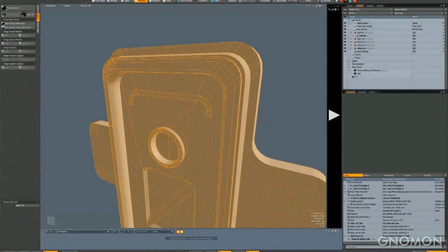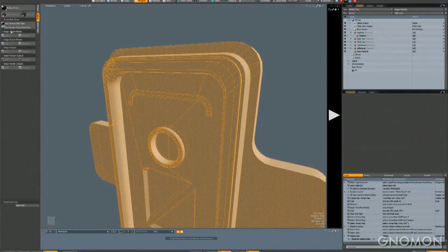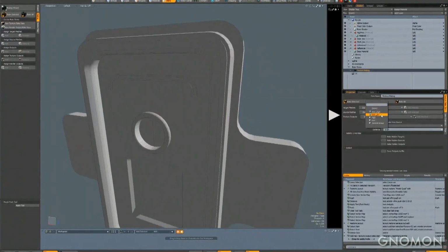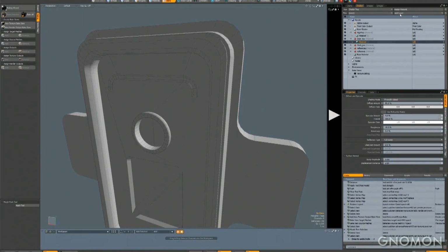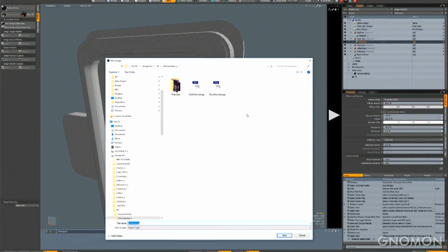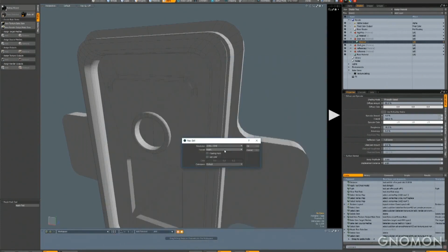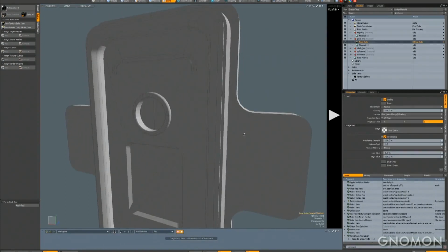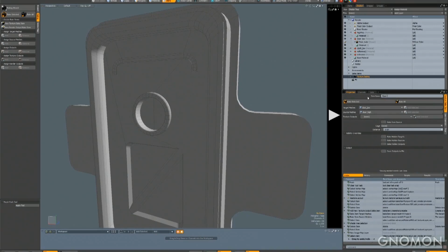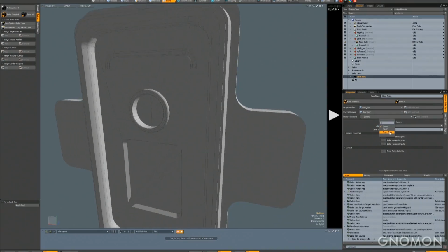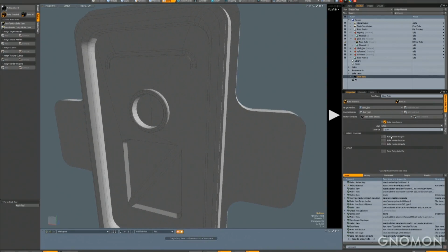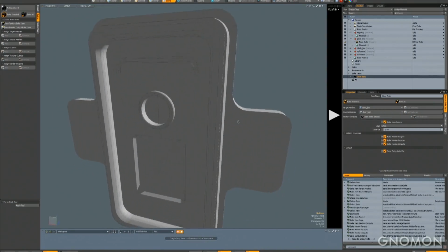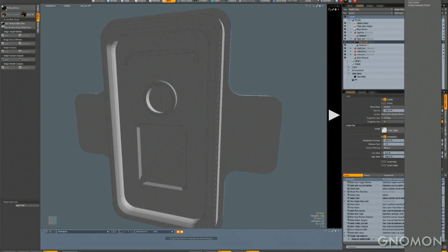And so we'll come back in here and make a new bake item. We set our target meshes and source meshes, which is the high poly. And we'll come over in here, and in the low poly material, which is the material assigned to the low poly mesh, we're just going to add an image, which is what our bake gets saved on top of. So right here, we'll rename the bake item door bake, select our cage, and select the image that we're going to be baking the normal map on top of. And just check all these boxes. And that's all there is to it.